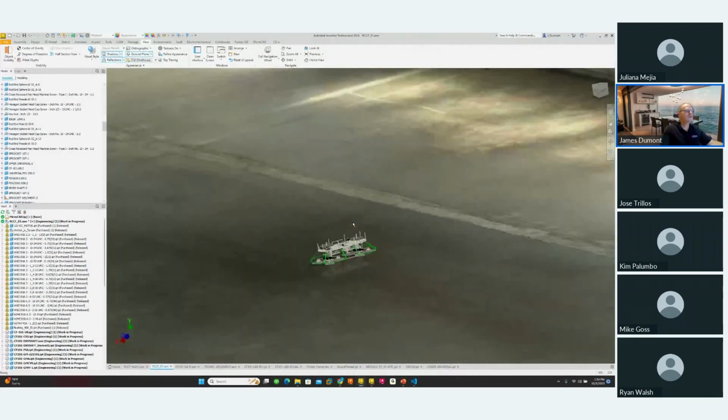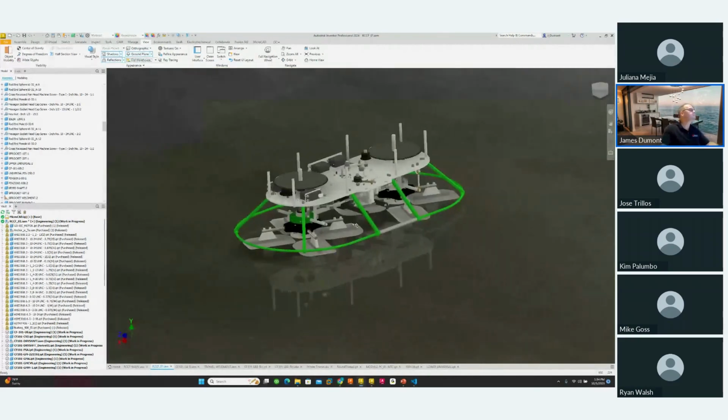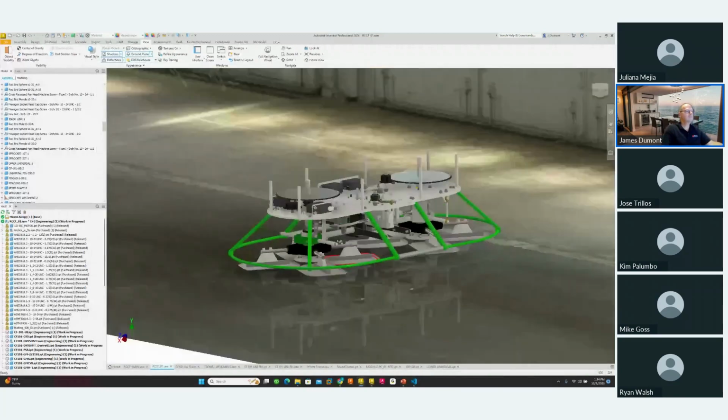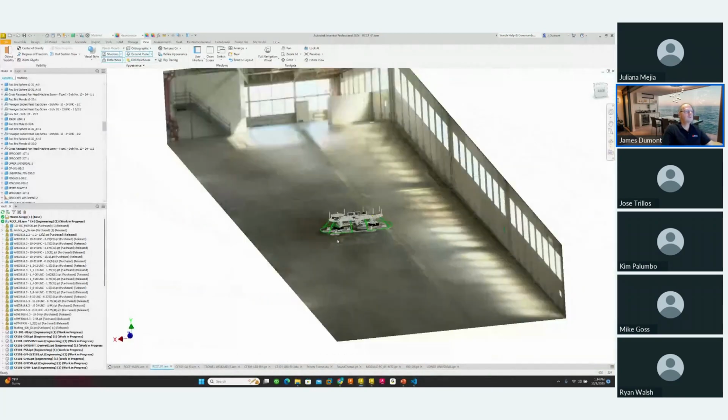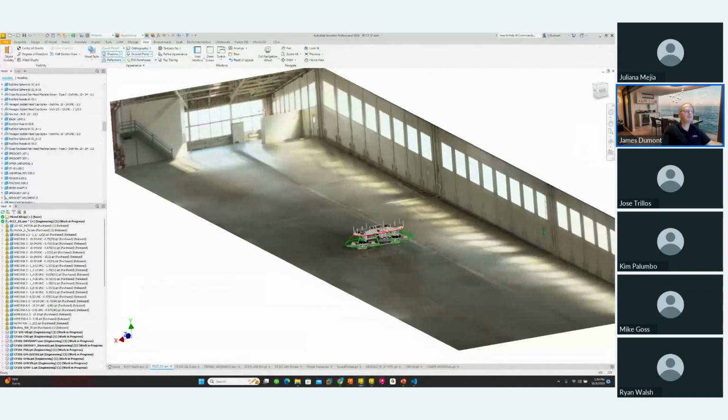So in order to work with this in the image-based lighting, if any of you have done any work with this at all, you have to go into your settings. And basically, it just puts a dome around your model, and it's a certain size. So what I'm going to do is scale this down a bit. Now, I'm not increasing the size of the model. I'm decreasing the size of the image-based lighting scene that's in there, and it just works better.